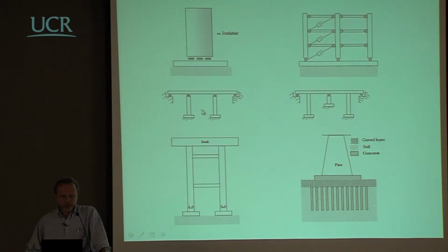But if we are talking about bridges, which is what I will be discussing starting from the next slide, the common thing is to have an isolation system at the deck level. And this makes the structure response completely different, because of course the piers are not isolated.